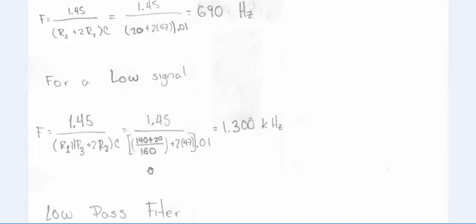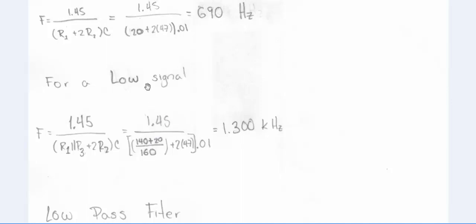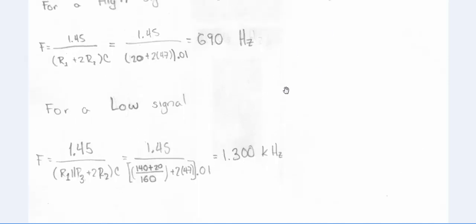So we decide to put the other potentiometer at 40 kiloohms and adding with the resistance of 100 kiloohms that is in series with it. We have 140 kiloohms plus the other potentiometer that it's the same as this. So we have that is oscillating in 1.3 kilohertz. So remember these values.